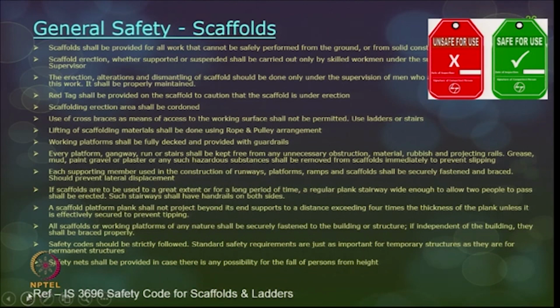General safety, again a recap on the scaffolds that we have talked about so far. Scaffolds shall be provided for all work that cannot be safely performed on the ground or from solid construction works. So, scaffold erection, whether suspended or supported, shall be carried out only by skilled workmen or by a competent authority under the guidance of a supervisor. The erection, alterations, and dismantling of scaffold should be done only under the supervision of a competent person, and even the maintenance of the scaffolds should be taken care of properly.